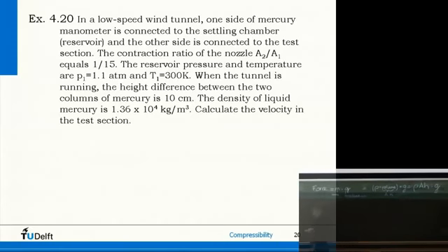So we still have an A in here for the force, right? Now, the fluid is at rest, so if we look at this height, we have an equal force pushing here as pushing here. So the balance of forces: on the left side we have P1 A. On the right side we have P2 A pushing, plus the force of this column, so plus rho g h times A. Now you see indeed we have A everywhere. The area of the tube, the area of the manometer, is not so interesting, so it drops out.